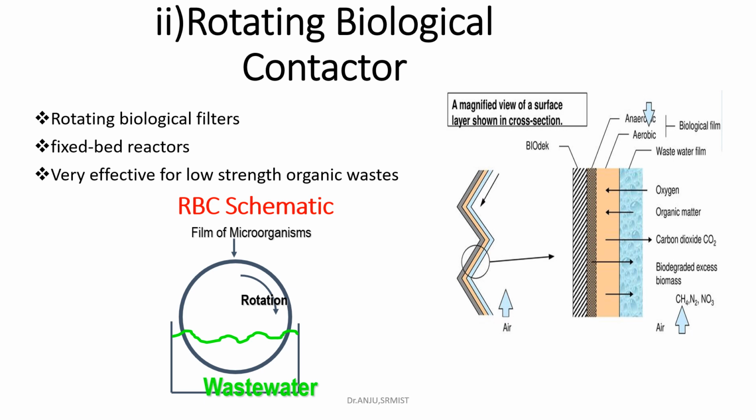But what is the difference is, here the microorganisms on the media come in contact with the wastewater by rotating the media in the wastewater. So it is by rotating the media in the wastewater that the biofilm interacts with the organic molecules present in the wastewater.